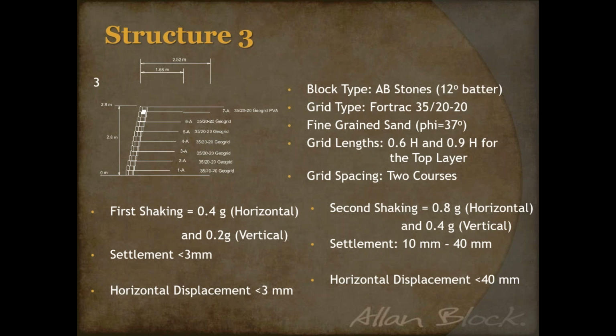You'll also notice there's a little bit of shading right here in this top couple courses. Why? Because at the time, the loading of the seismic was much top heavier than what we see today. And so connection strength, soil pullout, we would grout that top layer of grid into the block. And so we would physically pour concrete so that grid couldn't pull out of that system. And that was the way we would do like a positive connection. And we thought that would be a requirement based on the codes at the time, the methodology at the time.